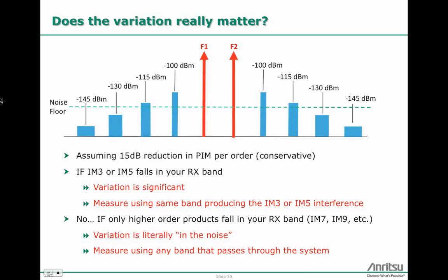So in that case, it really doesn't matter what frequency band system you're using to perform the test. It's going to help you find and reduce the IM3 level, in other words, improve the linearity, so that your system is going to be passing.